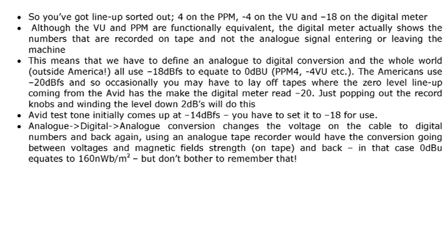If you think about the way that digital systems store audio as numbers on the videotape or in the memory or in the computer file, the analogy to that in the old analog systems was a signal strength on tape, a magnetic flux density on tape. And in case you wondered, 160 nanowebers per meter squared is the magnetic field strength for line-up tone on old analog tape, but not one to be remembered.